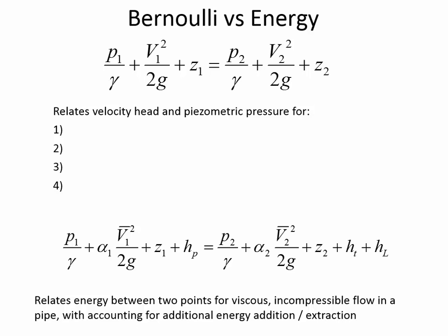So for instance, if we had the orifice problem, where did we choose as location 1 and location 2 if we were going to apply the full Bernoulli equation to this tank? All right, so we have the first location be at the top of the tank, and what advantage do we have of putting it there? Okay, the pressure head term cancels out to 0. Usually we have some elevation measurement to the top of the water surface, so that gives us a Z1. Also, if it's a large tank, the water level may be falling, but it's not falling very far, and that enables us to neglect the velocity head term, V1. So the main point is we're going to try and pick locations where we know a lot of things. We know the pressure, we know the elevation, we know the velocity, because then that allows us to focus on those limited things we don't know at the second location.